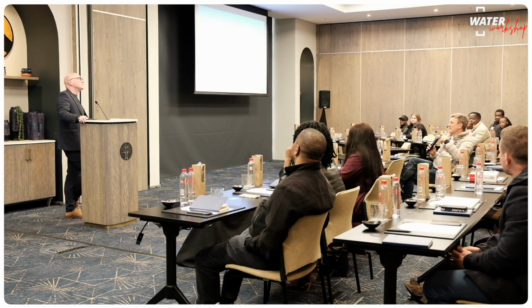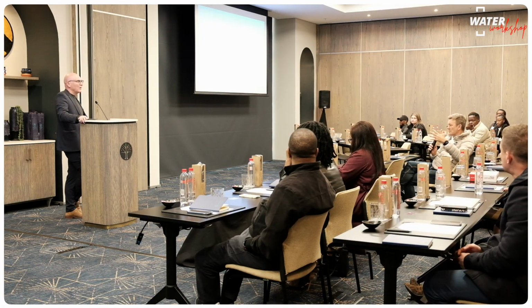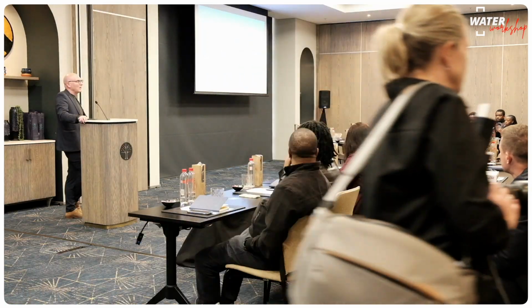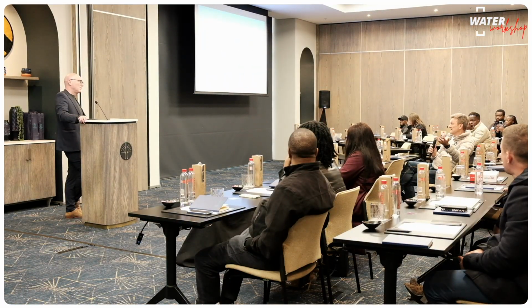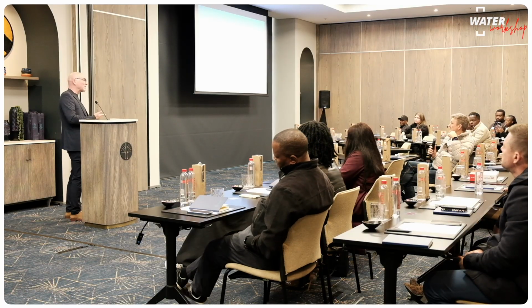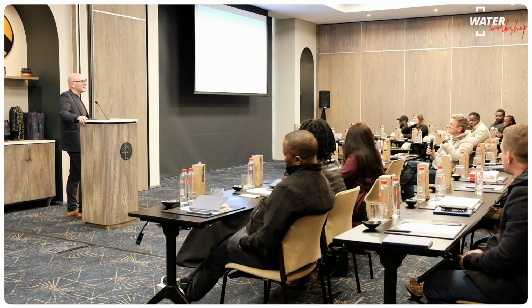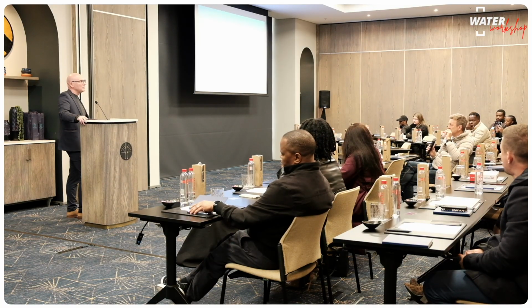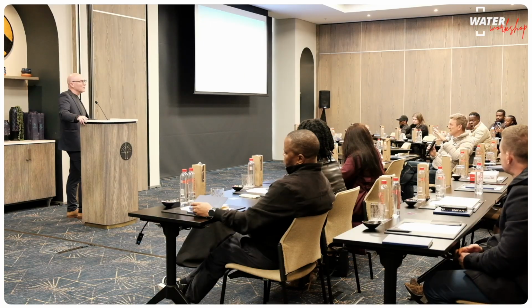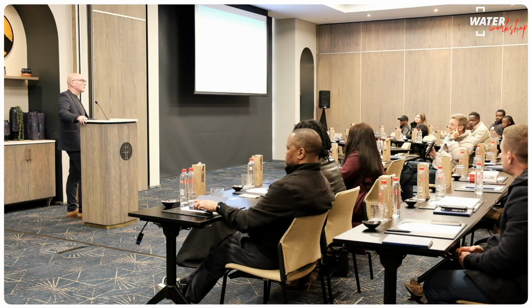But when you say managing, what's the function of the evaporator? It's presumably to completely remove the water, correct? So these are approaching ZLD water systems, and ultimately trying to get all the water out of the brine stream that is generated in an RO. So you're actually trying to precipitate the scale in that case. It's a long conversation, but I'm just not aware of anti-scalant chemistry that's applied in these thermal systems. I'm interested to see if you have that experience. Yeah. Okay.